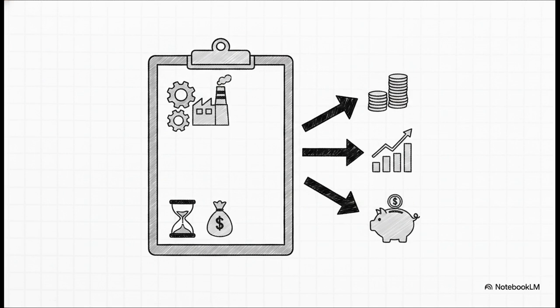The best audits identify simple operational changes, like, hey, maybe just turning off a specific conveyor belt during the lunch hour. They'll spot maintenance issues, like a clogged filter that's forcing a motor to overwork. They'll highlight where equipment needs replacing and propose new tech upgrades. But most importantly, a true energy audit gives you the exact costs, the projected savings, and the payback periods. It translates all that heavy engineering talk into a crystal clear business case.